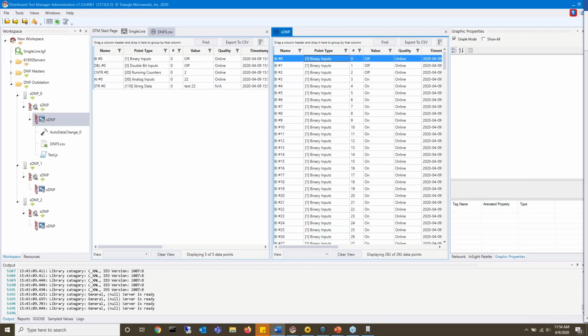First one, can we import the previously existing CID files for many devices here? Yeah, absolutely. Today I only showed off the SCD file because I wanted to show off the selector and the import substation. The SCL file, when you import, does not have to be an SCD file. I know I'm using a lot of 3-letter acronyms, but you can do any type of SCL file. That's IIDs, ICDs, CIDs, anything along your 61850 needs, you can import through there.